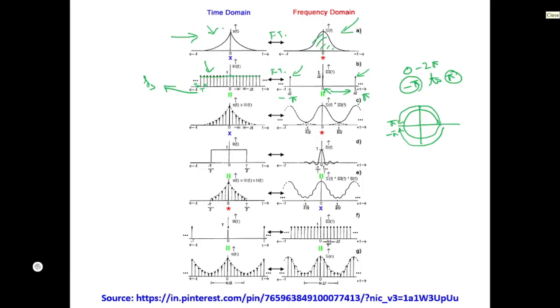At this sampling frequency component, when you multiply these two, we get this sampled signal. Now, when we have sampled this signal, the Fourier transform of this sampled signal has become periodic in nature. Before sampling, I said we need to band limit the signal. That means we had to apply a band pass filter to restrict the frequency components.